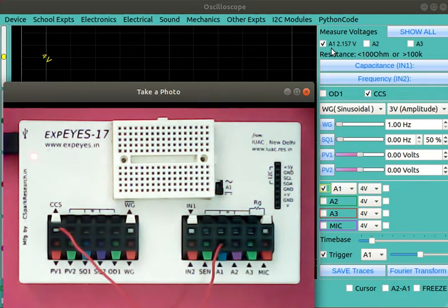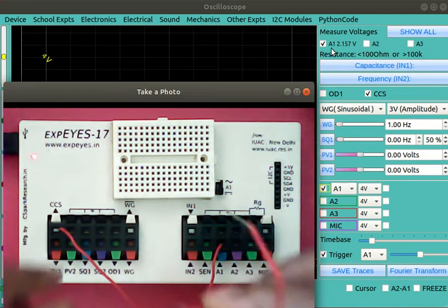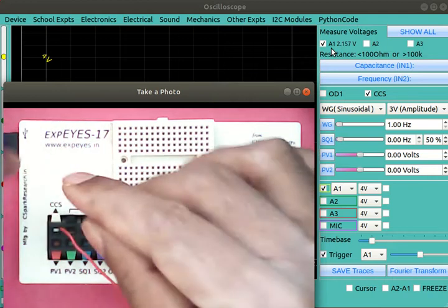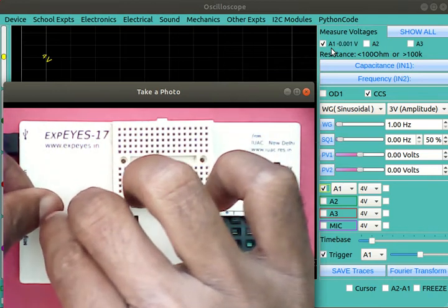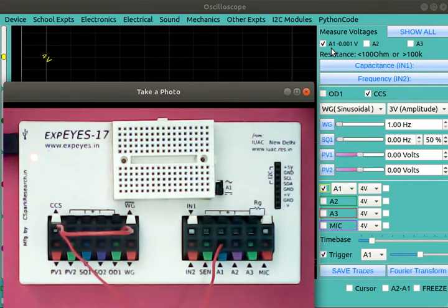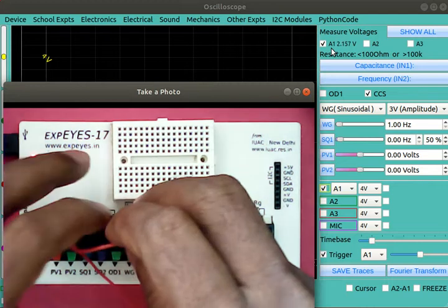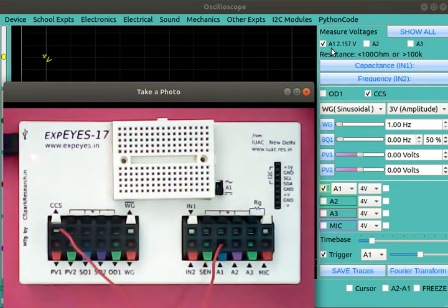See, it is showing some high voltage because the resistance is gone, right? That is the reason. And if I just short circuit that to ground, then it goes to 0 volts. So generally the usage is you connect something like a resistive sensor like a PT100 or something to it to measure temperature. That is the actual usage of it. So we will not worry about that now.